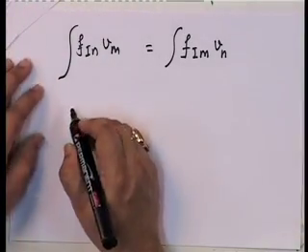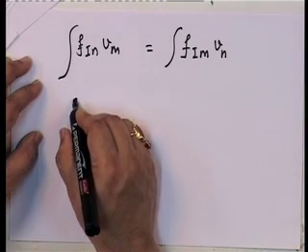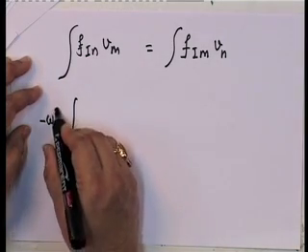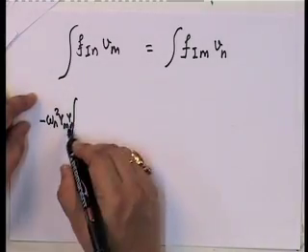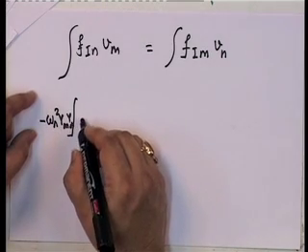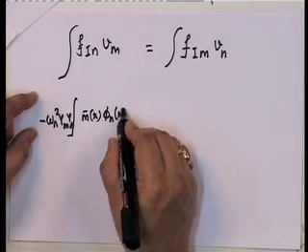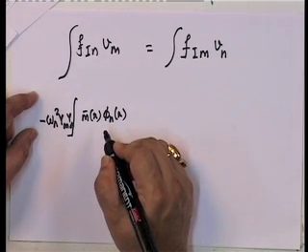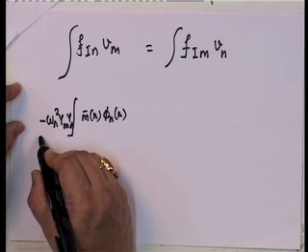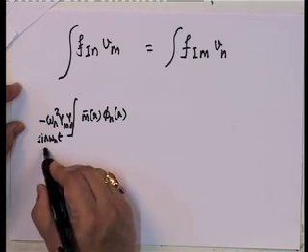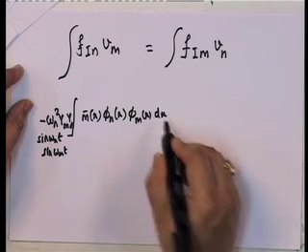So if you look at this, if I plug it in, what do I get? I get Fin, I'm going to substitute, and Vm I'm going to substitute. So I'm going to get minus omega n squared ym yn, because ym comes from this, yn comes from this, omega n squared comes from this. This is going to be equal to m bar x phi n x, into, of course, in this particular case you have sine omega mt and sine omega nt. So here sine omega nt and sine omega mt will come outside. It's going to be equal to phi nx phi mx dx, right?